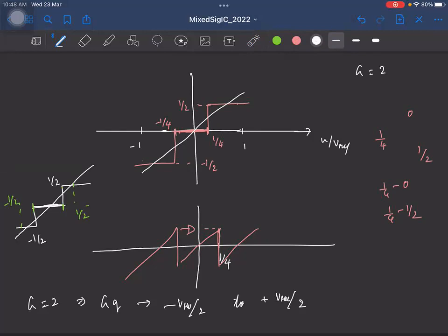I have 3 levels, right? No, 2 bits can represent effectively four levels. So you just have 3 levels. What is the effective resolution? How can you find out? Okay, if I have 8 levels, you say it corresponds to 3 bits, right? How do you say that? Log to the base 2, right? So we have 3 levels. Effectively, it's log to the base 2 of 3. Okay, this roughly it's 1.5 bits. So this is usually called the 1.5 bit stage. Okay, or 1.5 bit ADC. But obviously, you need 2 bits to represent the output. But it has an effective information corresponding to only 1.5 bits.